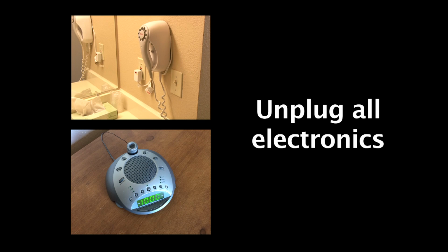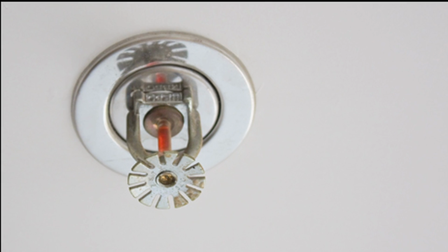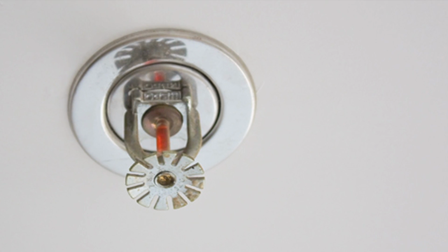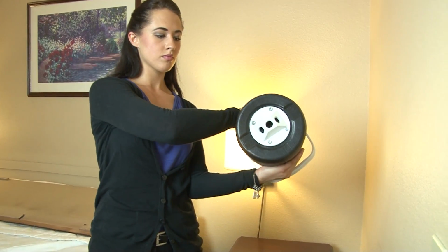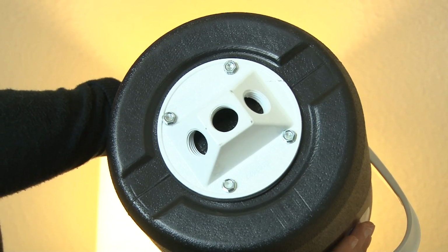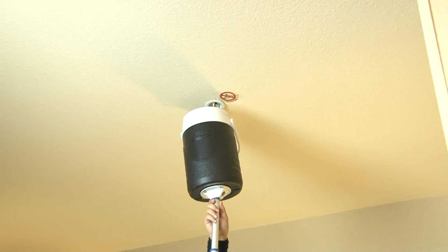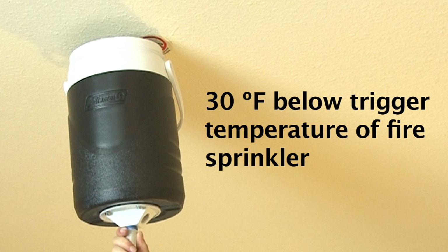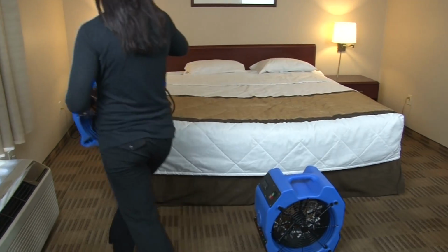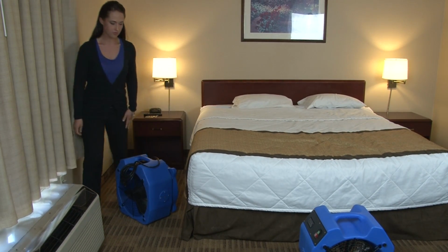Next, unplug all electronics. If your hotel has a fire sprinkler system, we recommend that the heads be drained and capped before the heat process commences. If this is not an option, we do have techniques to protect the heads in place during treatment. Always keep the heat level at the fire sprinkler head at a minimum of 30 degrees Fahrenheit below the trigger temperature of the fire sprinkler.